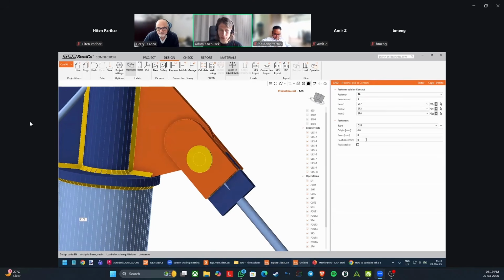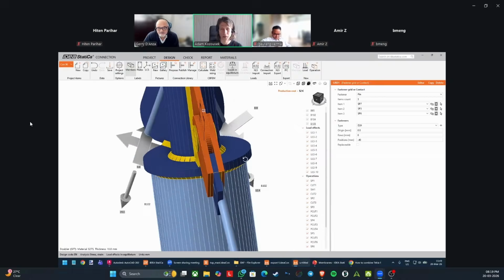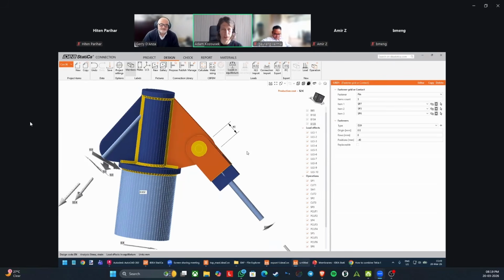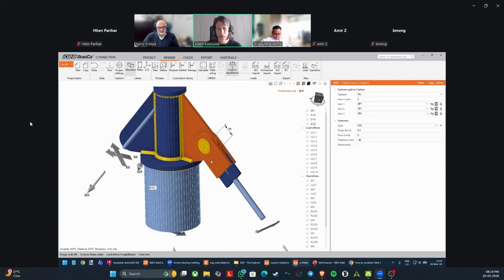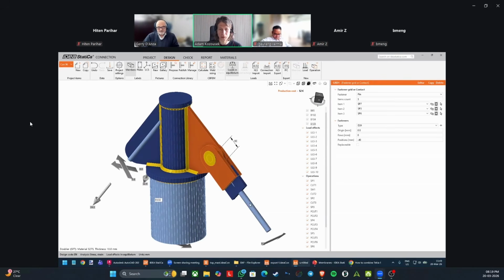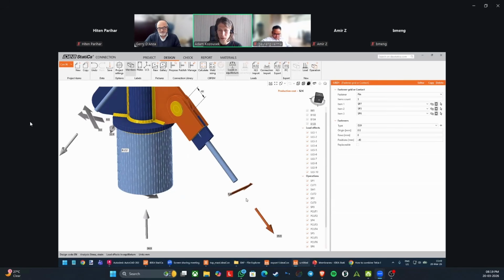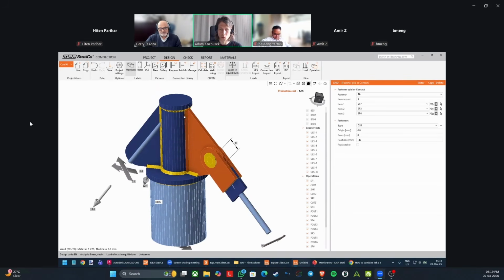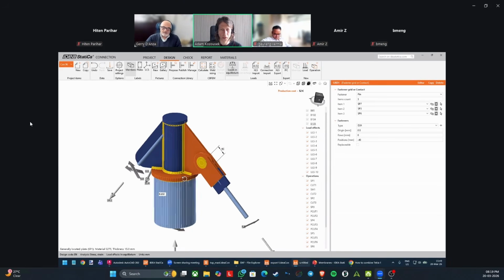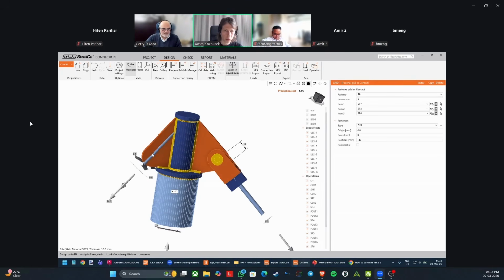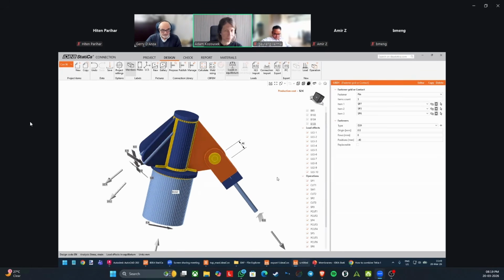And basically, you can position the pin like this. So now it looks like this. Okay. And that should be it. This is how I simulate this connection, right? So now I'm able to transmit this tension and this little tiny shear force in the cable into the connection and calculate it.